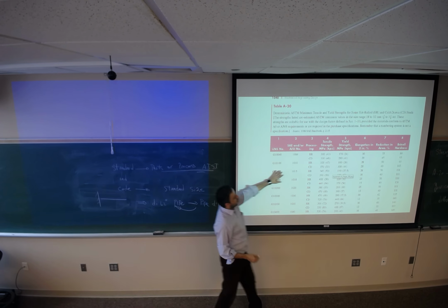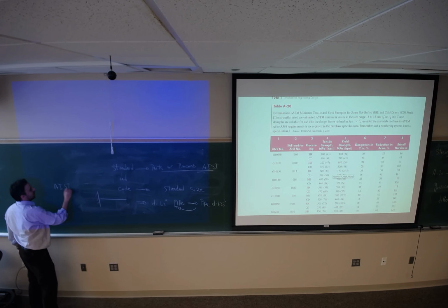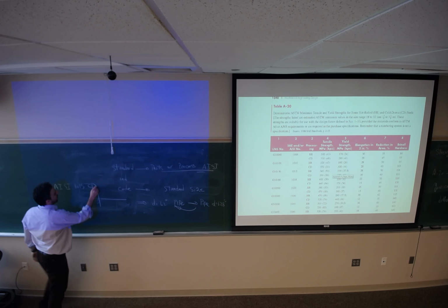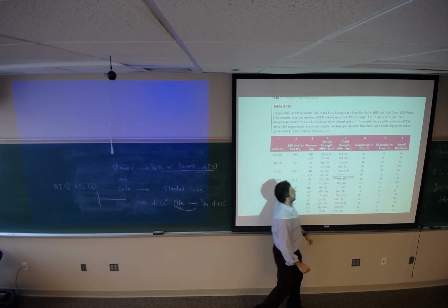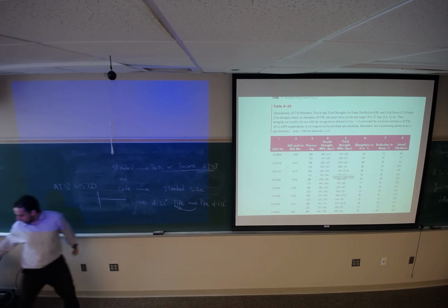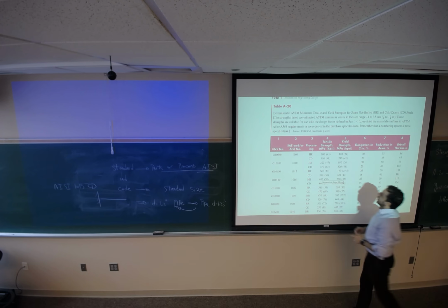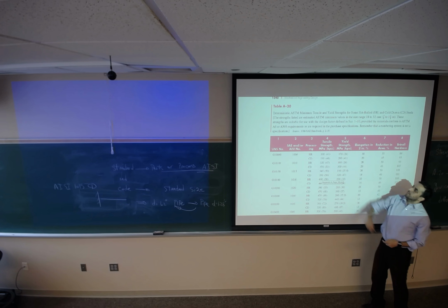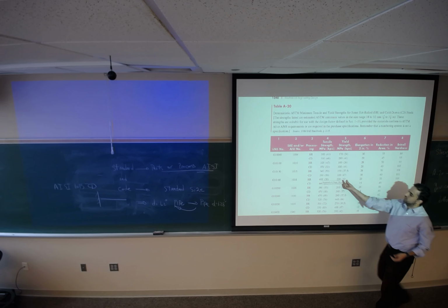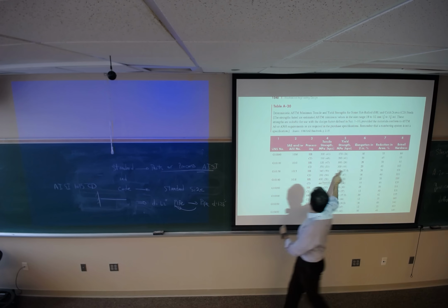So if you are given, for example, a material made of AISI 1015, cold drawn, you can look at this table, find 1015 cold drawn, and get this information: 390 megapascal for tensile strength, and the yield strength is 320. If you are looking for PSI units, you can look at these numbers: 32 kpsi, kilo pound per square inch, and 50 and 27.5.